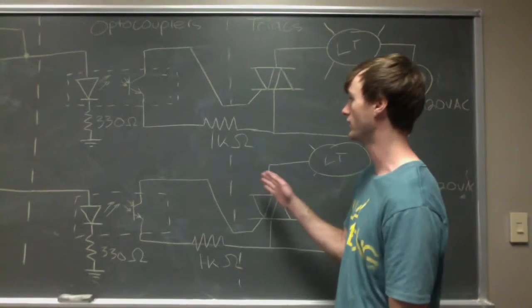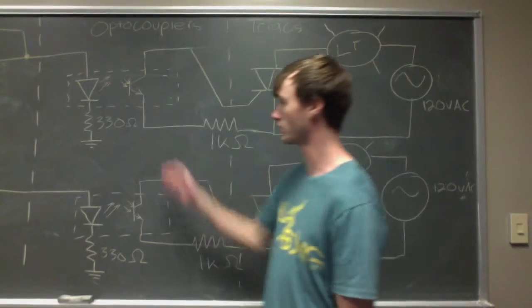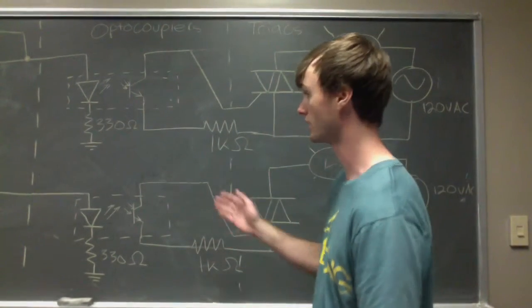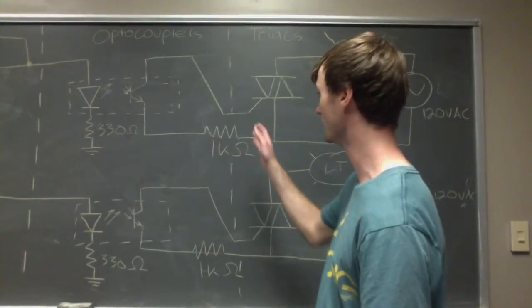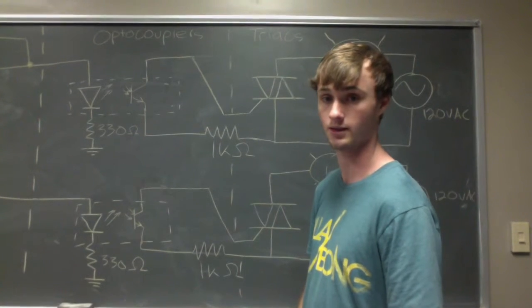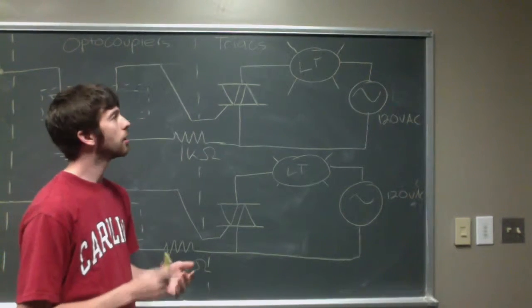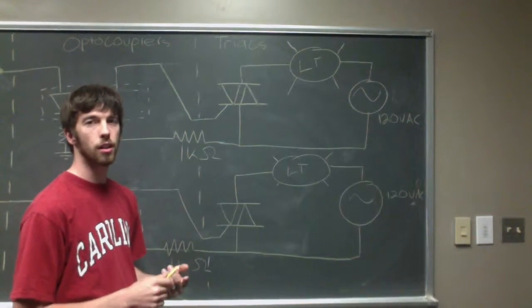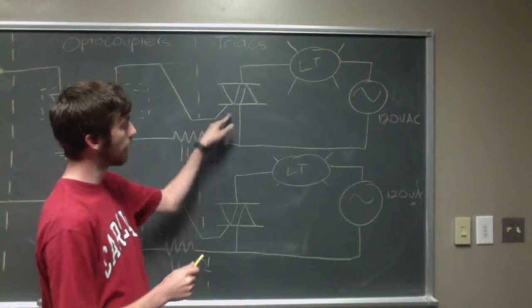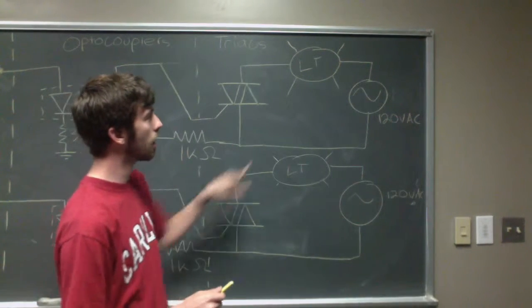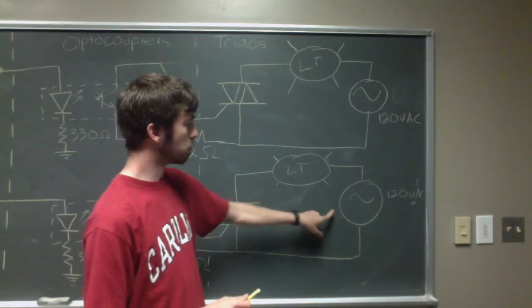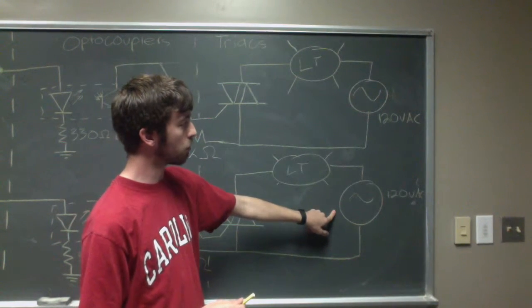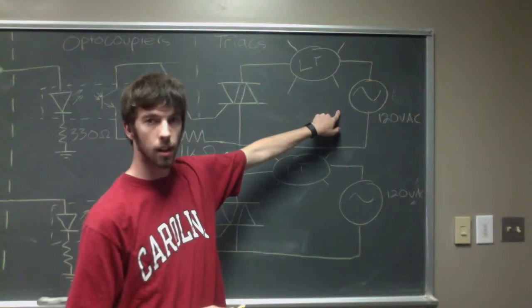In our third phase, we implemented our optocouplers, which connected our outputs from our two filters to the gates of both triacs, connecting our lights. The fourth subsystem of our circuit involves two triacs that are used to switch on a red light and a green light. And those lights are both powered from the 120 volt AC.